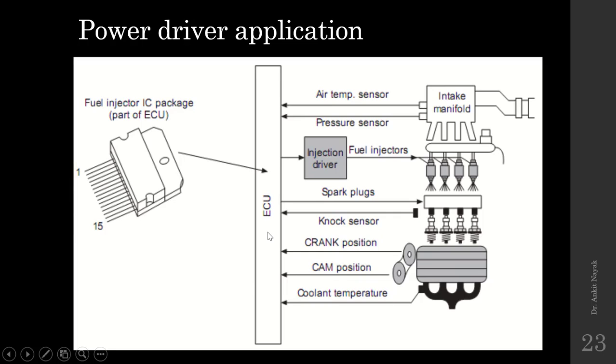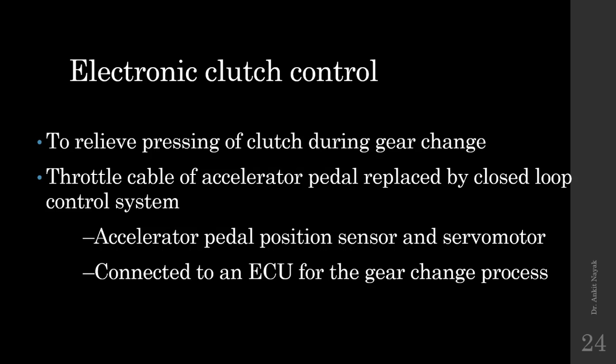These are some input variables, and accordingly we have to set the output variables like the spark ignition timing, or the fuel ignition timing, or the amount of fuel which we have to supply inside the cylinder.